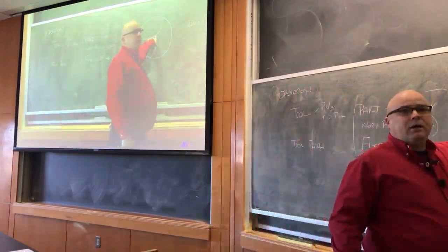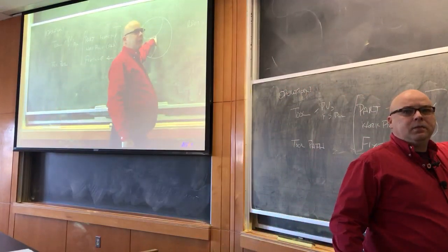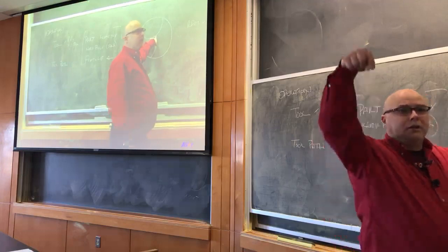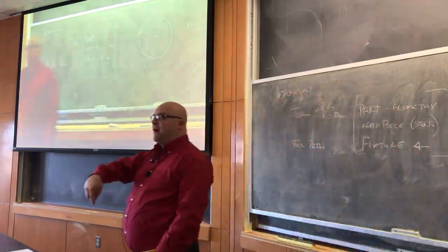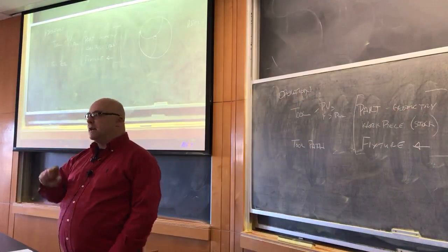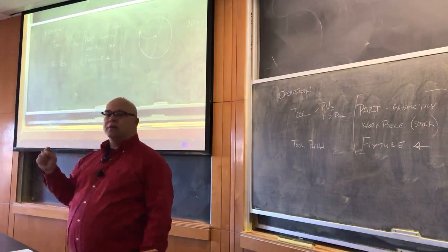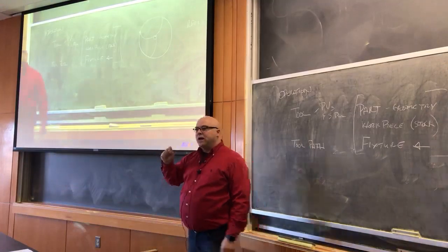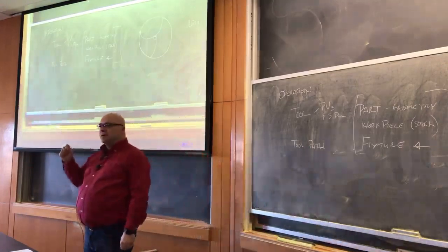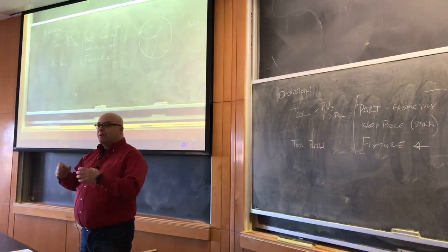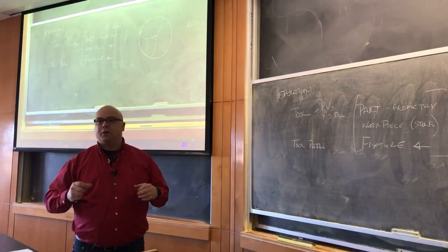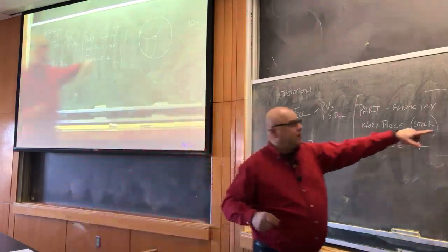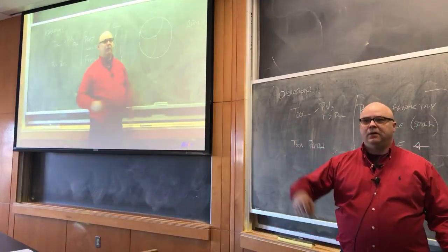So the surface speed here, no matter what, will be 0. Which means these tools do not really like to plunge down into the workpiece material. Can it cut? All of the cutting comes from the surface speed. We said that a couple lectures ago. All of the chip formation, all that cutting happens because of the surface speed. Now, the feed rate and the depth of cut puts the tool in the position where it's able to cut. But the cutting happens from the surface speed, which means there is no cutting happening at the center of the tool when it plunges down.